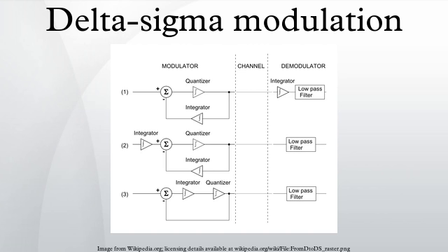Remarks: in this section we have mainly dealt with the analog-to-digital converter as a stand-alone function which achieves astonishing accuracy with what is now a very simple and cheap architecture. Initially the delta-sigma configuration was devised by Inose and colleagues to solve problems in the accurate transmission of analog signals. In that application it was the pulse stream that was transmitted and the original analog signal recovered with a low-pass filter after the received pulses had been reformed. This low-pass filter performed the summation function.